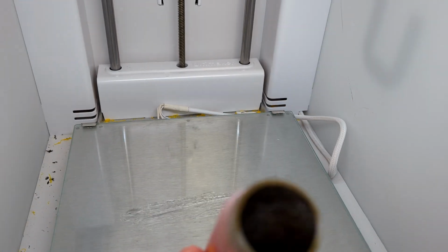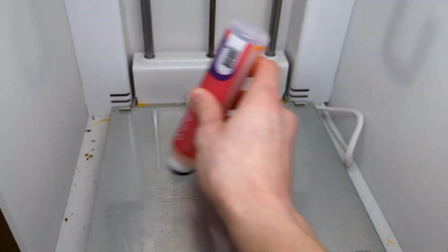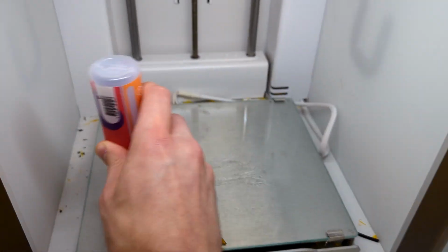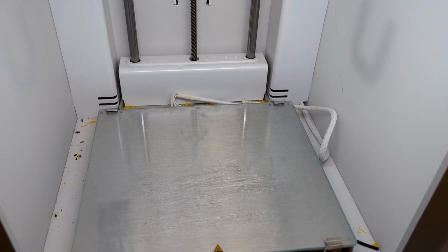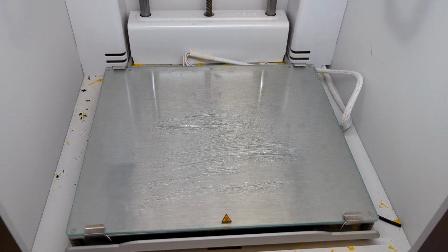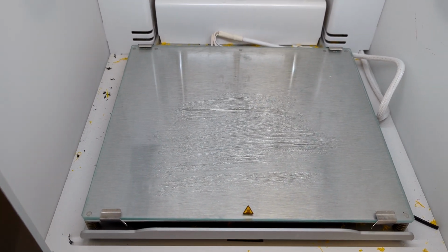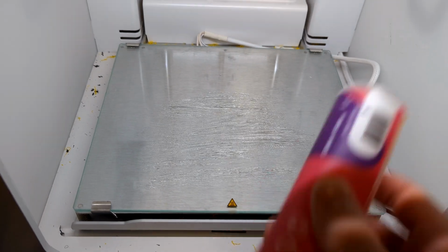Now, see how there's a sponge on the tip? You use the actual bottle to apply the glue on the whole bed. And if you're just printing a small thing in the middle, you don't have to apply it on the whole bed. You can just put it in the middle. If you didn't level the bed and you see someone already put glue, you can use that same application of glue for your print. You don't have to put a new application of glue each time.